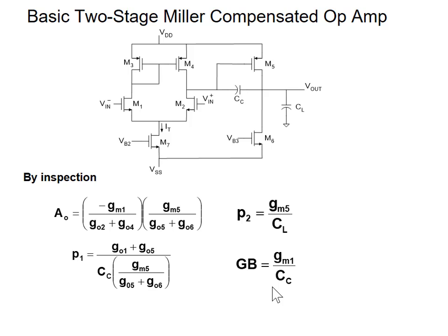Why do some people like to use the criteria that if the phase is negative 180 degrees and the magnitude is greater than 1, it's unstable? Are they just using different words to say the same thing that we're saying here? Well, first of all, I regret using the term stable or unstable. If you're worrying about whether an amplifier is stable or unstable, you've got a lousy amplifier.